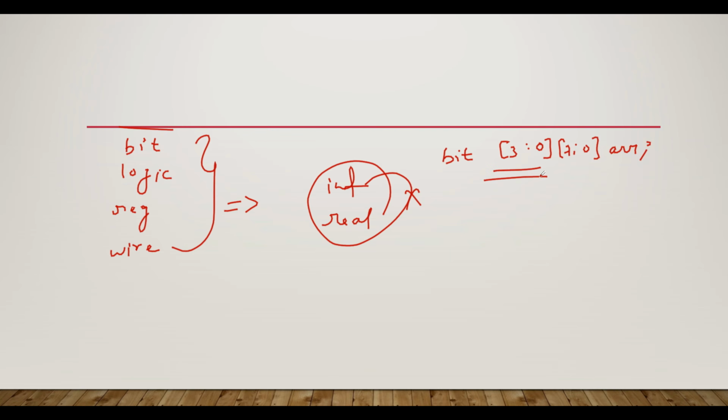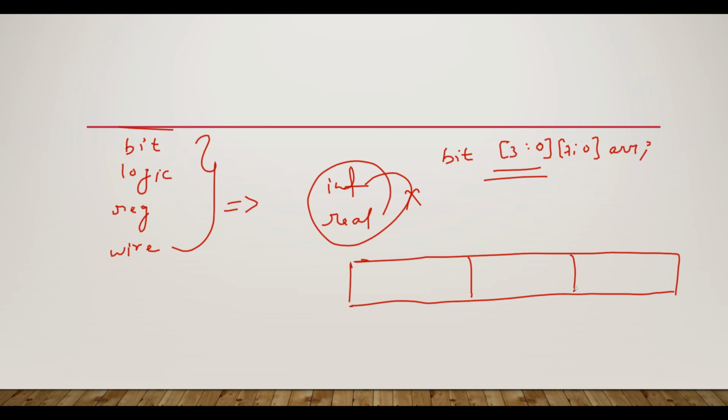First of all, the first dimension is 4 bits, so you can consider one block of 4 bits, which is separated into 4 blocks internally. Then again here we have 8 bits, so each block consists of 8 bits: 1, 2, 3, 4, 5, 6, 7, 8, and a similar thing goes with the others. So you can declare your memory location something like this in a packed array.